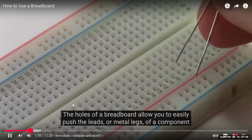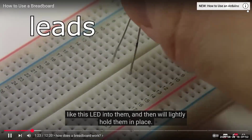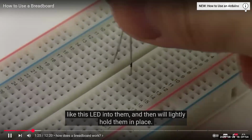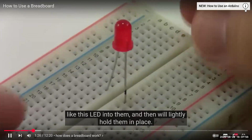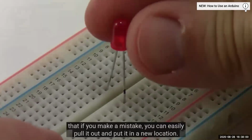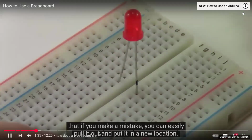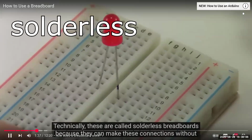Some breadboards allow you to easily push the leads of components, even an LED, into the holes, and that will lightly hold them in place. This connection is strong enough that the LED won't fall out on its own, but light enough that if you make a mistake, you can easily pull it out and put it in a new location. Technically, these are called solderless breadboards because they can make these connections.